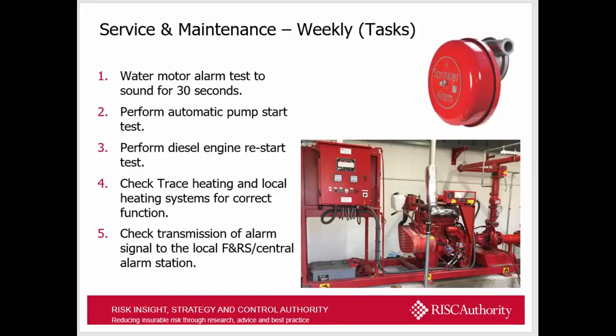function. Most of the time when I do a sprinkler inspection, I go into a pump house and it's cold, and the heating system's not working. Well, if you have a diesel pump in a pump house, that pump house has got to be maintained at 10 degrees C. And then obviously you have trace heating panels. They need to be tested on a weekly basis. And any transmission of signals to the local fire and rescue service or central alarm stations, they should also be checked. And again, these are tasks that are required of the site staff.